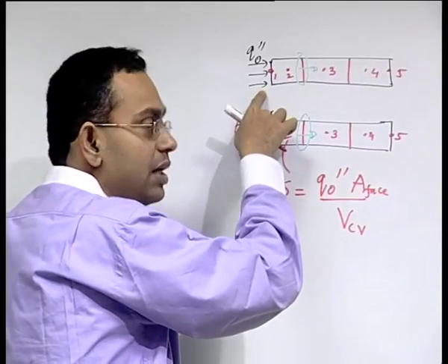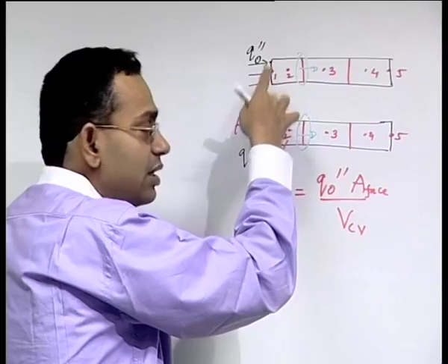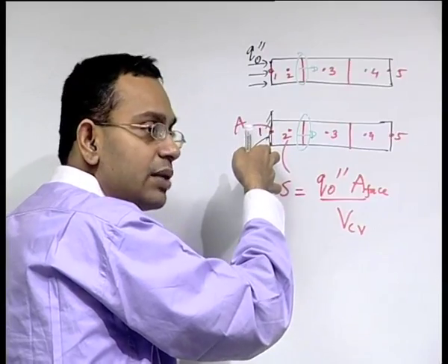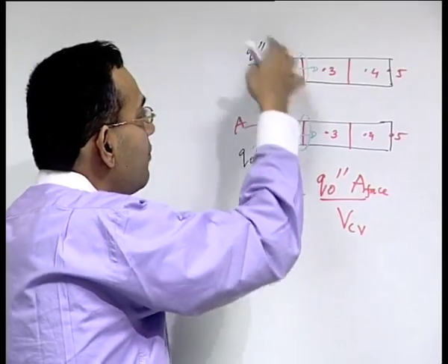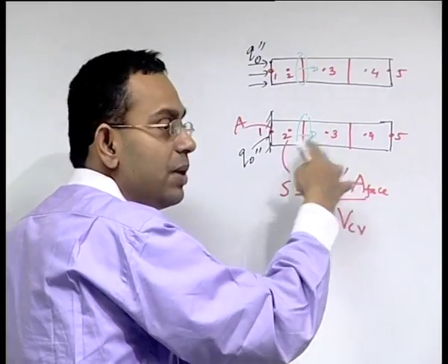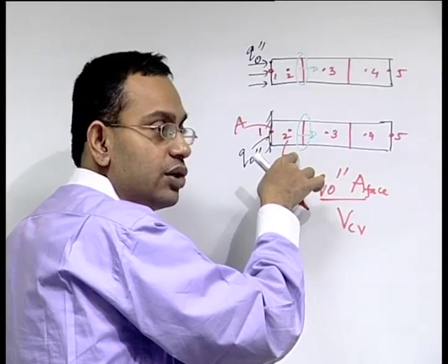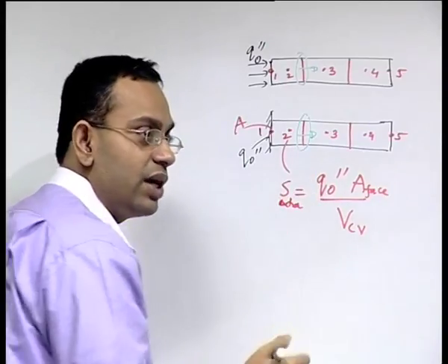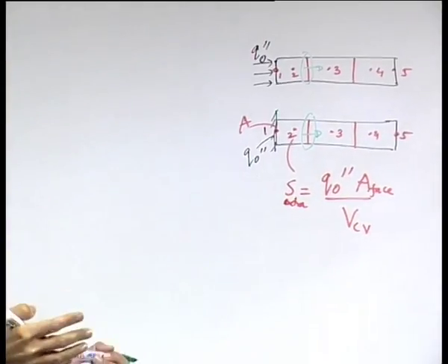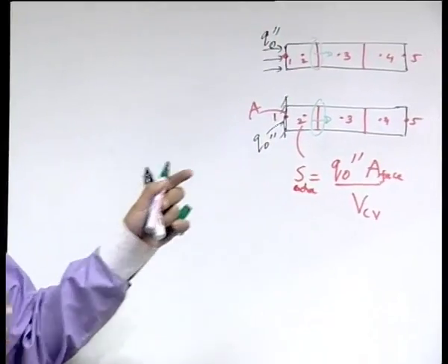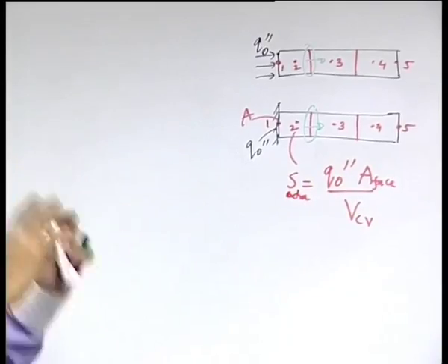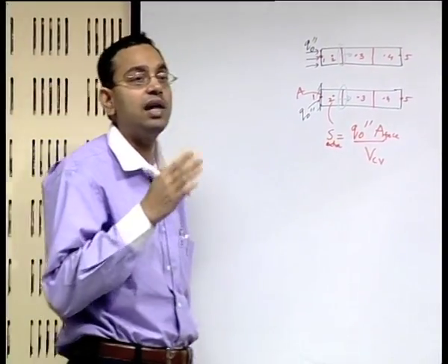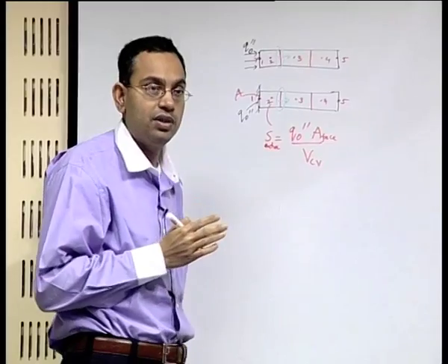So, for implementing a constant heat flux boundary condition, sometimes what one can do is consider an insulated boundary condition, and whatever was the heat flux there, dump it as a source term in the corresponding adjacent control volume. This source term, remember this S extra. If there is some other source term, this is not that one, it is whatever was the other source term plus this extra source term to compensate for the non-consideration of the heat flux at the boundary where it is actually there.